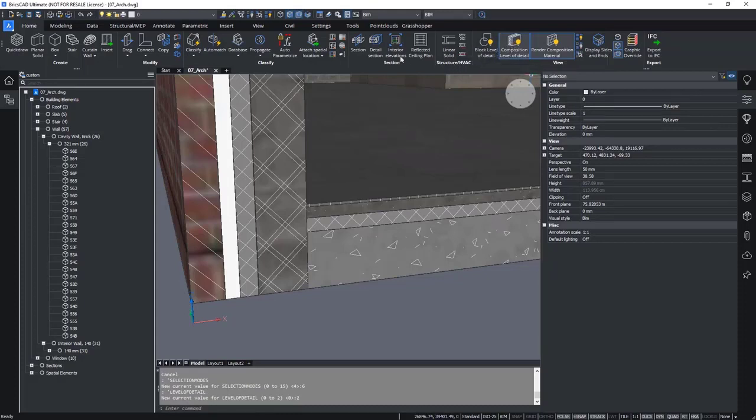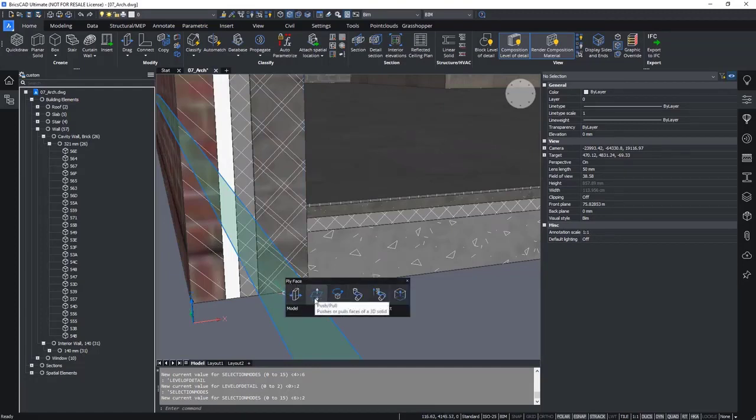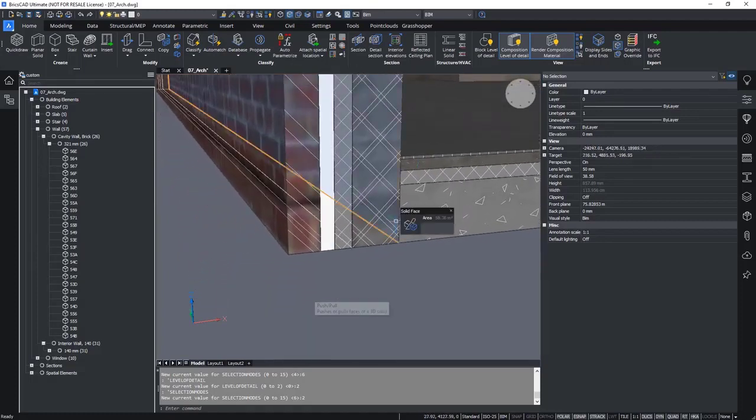In your selection modes, make sure that maybe only prioritize selection of faces is enabled. A bit easier. And then you can see that as soon as I hover near the end of a certain ply, the ply face is highlighted, and you will be able to do some actions such as push-pull. So here, let me cycle, and cycling through this sub-selection underneath your cursor can be done with Tab. If I have the ply face here,